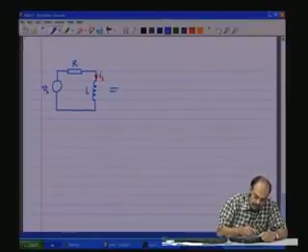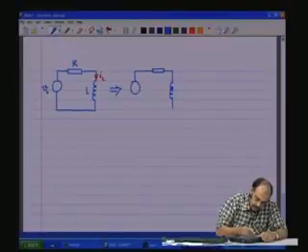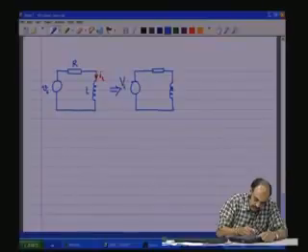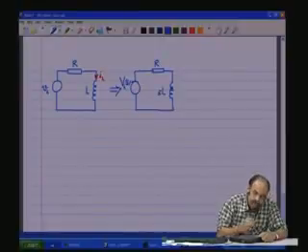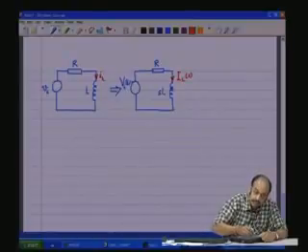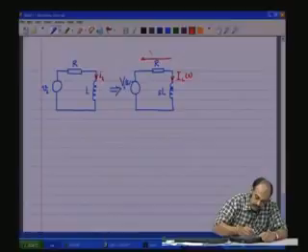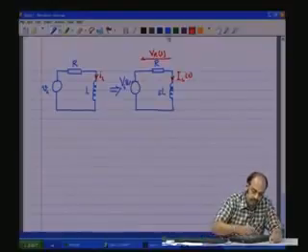Now, we take the circuit to the Laplace domain by the simple process of replacing j omega in the inductive reactance with S, and then we also capitalize all the variables and they become functions of S. This is R, and then you have L, and now the reactance would be S L. We have I L S as another variable here, and if you want the voltage across R, it is V R S. All in the Laplace domain, with the Laplace variable S coming into the picture.